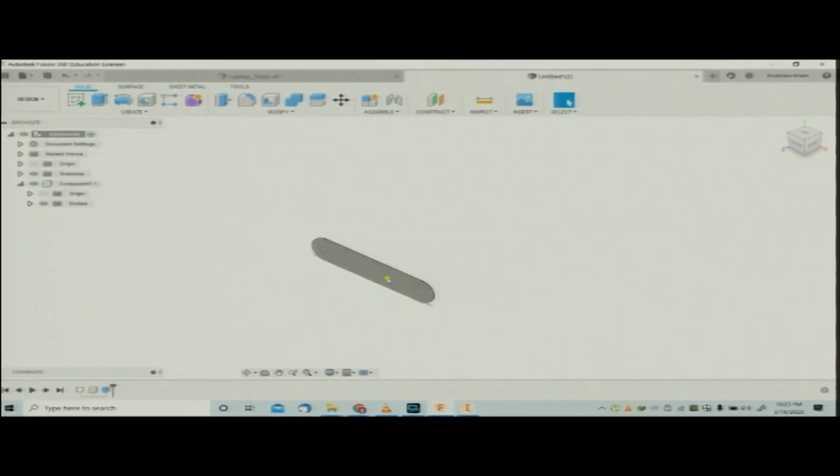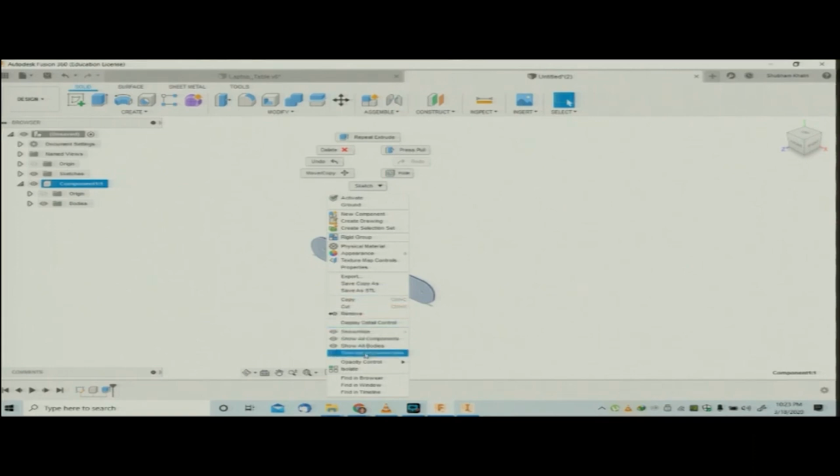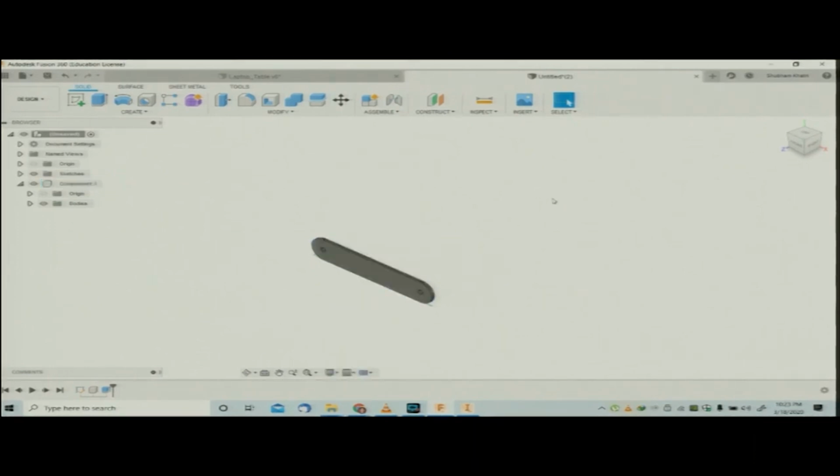Okay. Now this component is to be copied. What do I do? I double click on my geometry, select the part, right click on it, then I copy it from here and we can paste it here. Paste and paste new. Again, paste and paste new, 2 options are there. When I say paste, it will just paste as a copy of this, and any change in the primary component would reflect in the further components that are made from that. Paste new would be an independent component in which the changes can be made independently. So paste new is the one that I would like to do here.